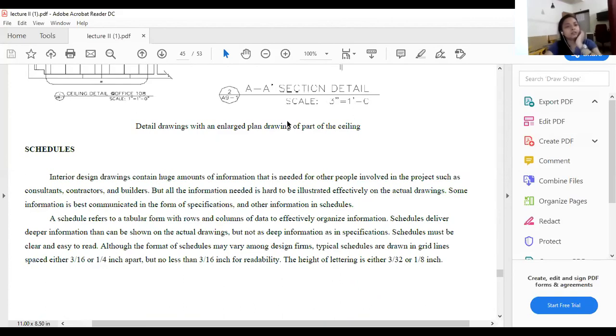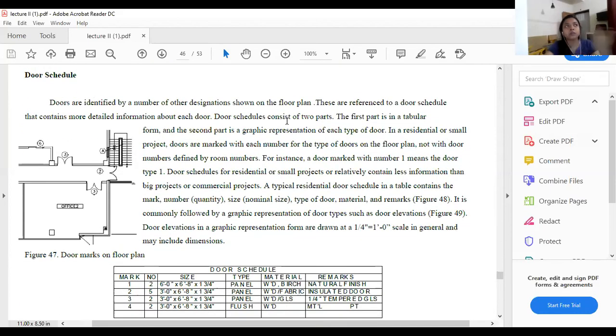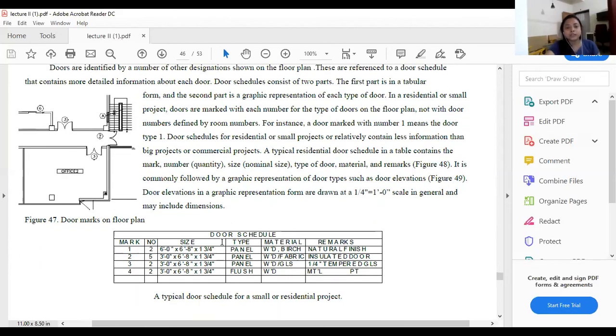Now, moving further, I would like to talk about these schedules of doors and windows. For any kind of technical drawing, whenever you are going for working drawings or BDA approvals, everywhere it is very important to give the door and window schedule of your drawings. Whatever your plan layout, there must be different sizes and specifications of doors. So this should always be mentioned in a door and window schedule.